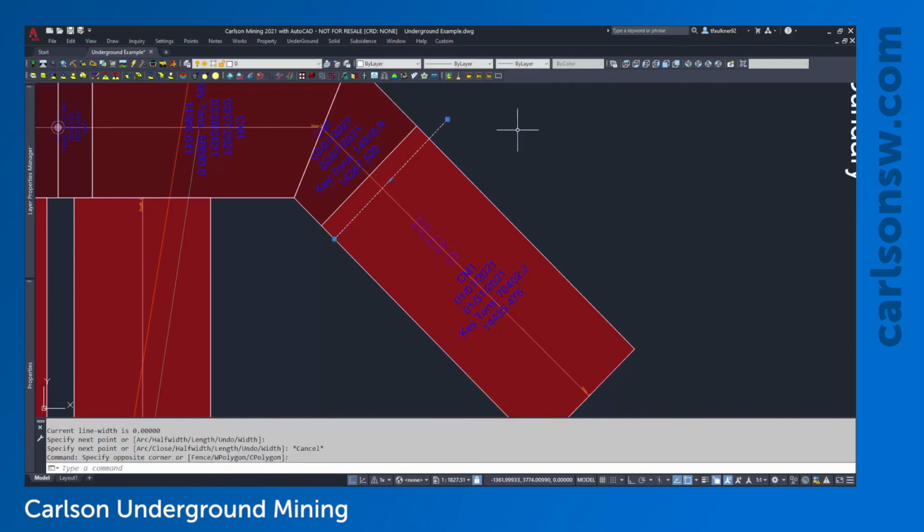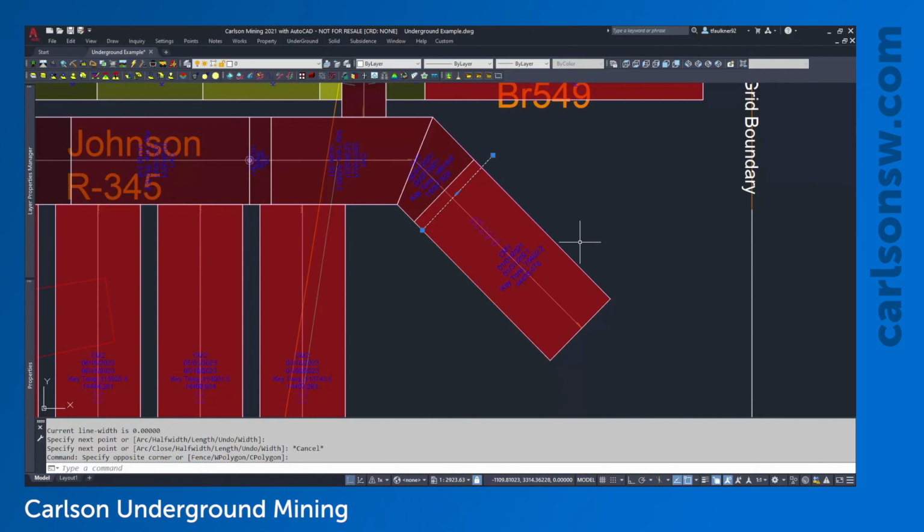And we want to recalculate the timing as if we were to basically have everything up to this point mined out, but starting on February 1st. We don't have to delete this panel. We don't have to modify the original line work, but we can set a current position in the mine to account for that change. So what I'm going to do, I'm going to go to underground.